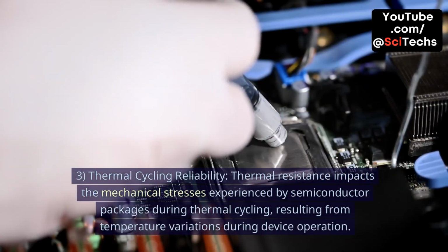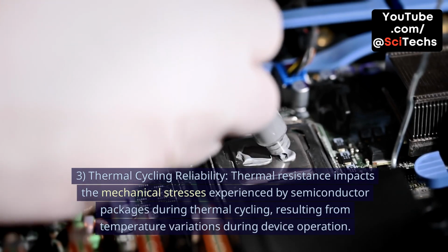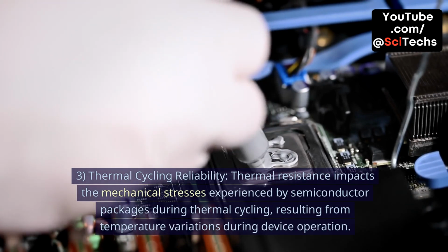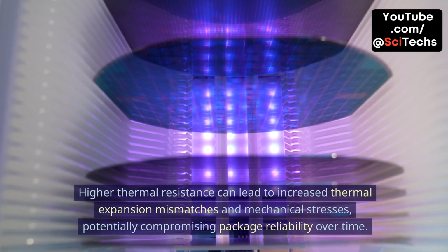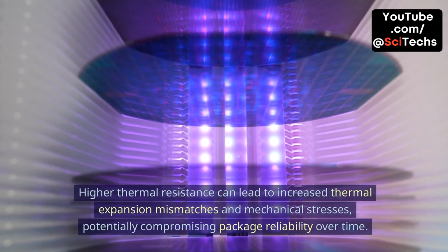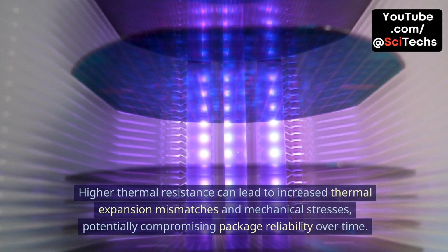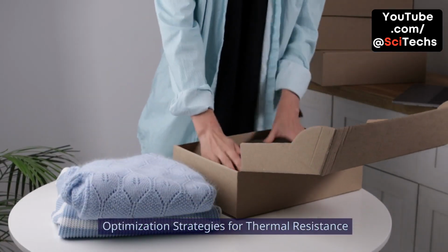3. Thermal cycling reliability. Thermal resistance impacts the mechanical stresses experienced by semiconductor packages during thermal cycling, resulting from temperature variations during device operation. Higher thermal resistance can lead to increased thermal expansion mismatches and mechanical stresses, potentially compromising package reliability over time. Optimization strategies for thermal resistance.